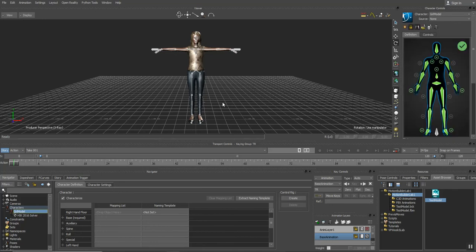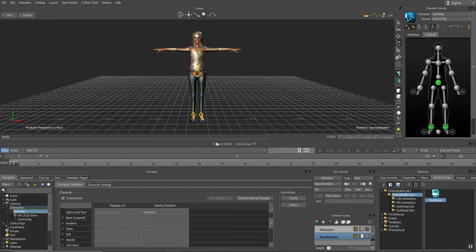Alright, so the pose control works with the control rig in Human IK. If we go up to the Human IK button here, we could create a control rig for our character. We're going to create an FK-IK rig for the character. The FK-IK rig is great because you can grab all the different joint controls on the character controller and edit those.